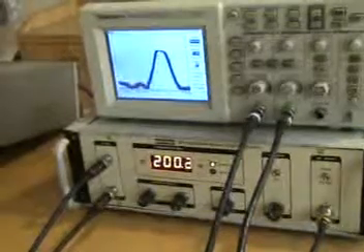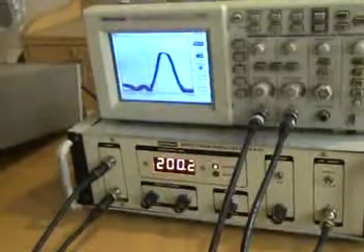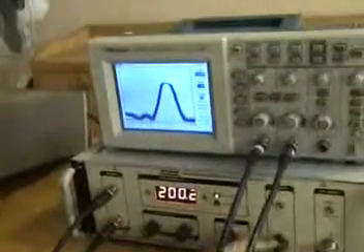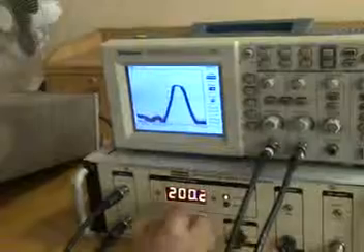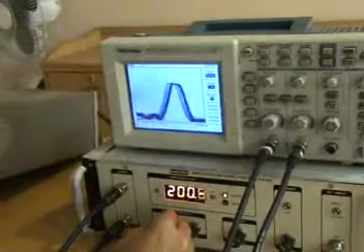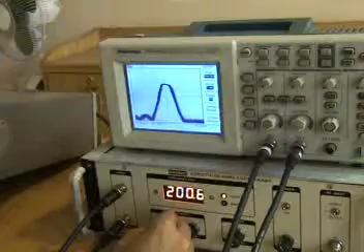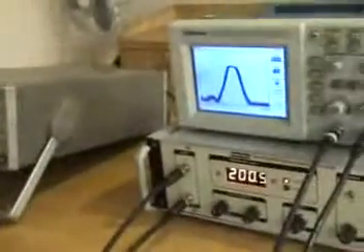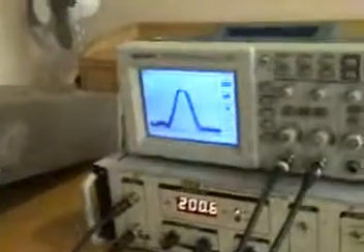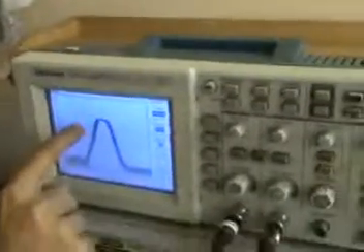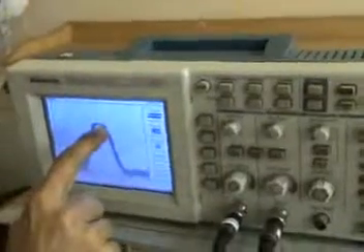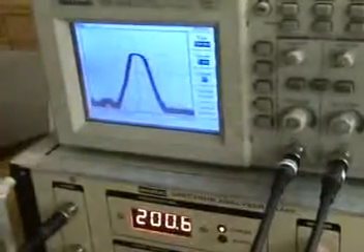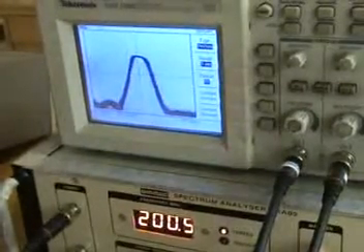Input is always 50 ohm, and IF bandwidth is 250 kilohertz, because if you put this in the center and each division is 100 kilohertz, as we had discussed, by changing the source by 100 kilohertz. So if you see the IF bandwidth, the 3 dB bandwidth is equal to one division, that is only 100 kilohertz.